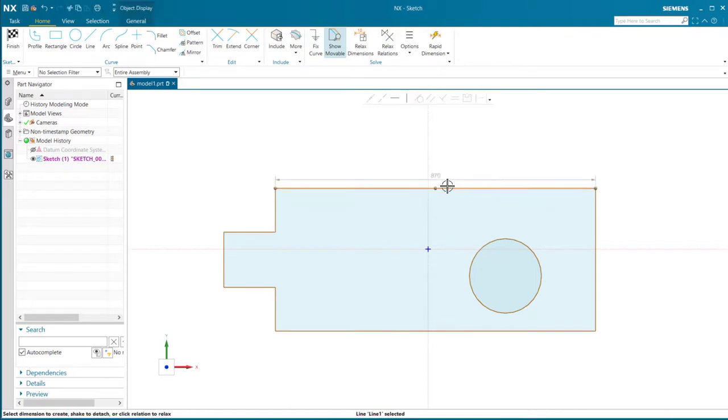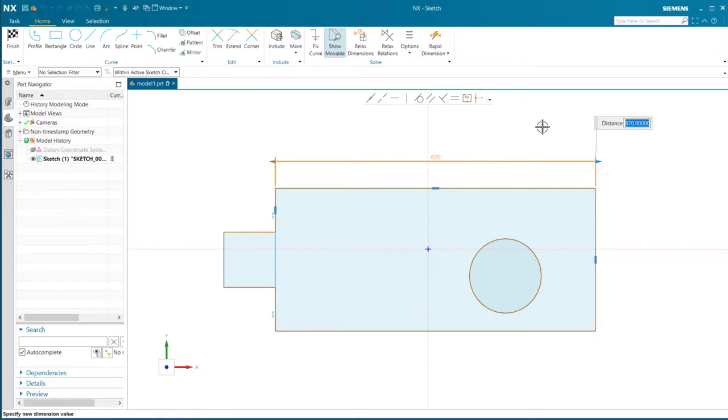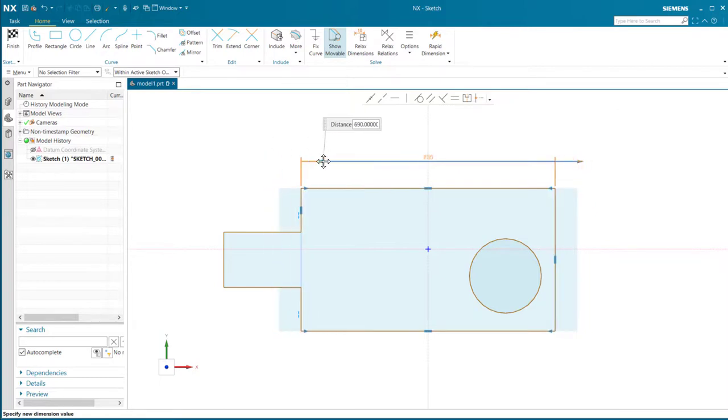Now, as far as creating a dimension, you basically just select a line and then click, hold, and drag, and notice it's then selected. Now, here's where the user interface works with the solving, and the power of the new sketch is basically that it allows me, at this point, to drag just this line, and then anything associated with it will move with it. And if I select this side, both sides move at the same time, as you can see here.